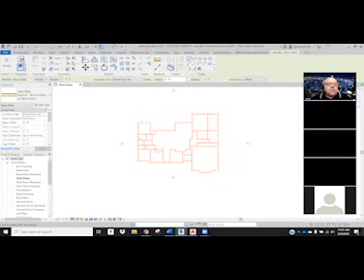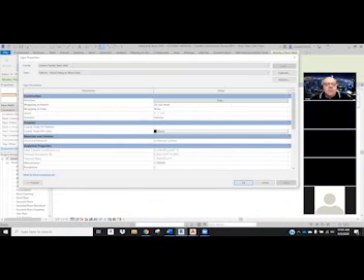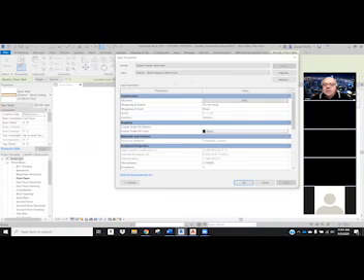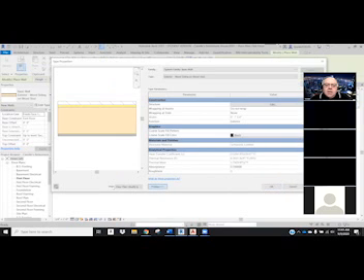All right. Now, before I can draw, I need to, again, make it a stucco wall. So we're going to hit Edit Type, right below the name. And we're going to get this big old section window. I'm going to minimize that down or stretch it in just a little bit. You can hit a preview button down here in the bottom left corner, and that'll show you what the composite of the wall is. Composite meaning things put together.